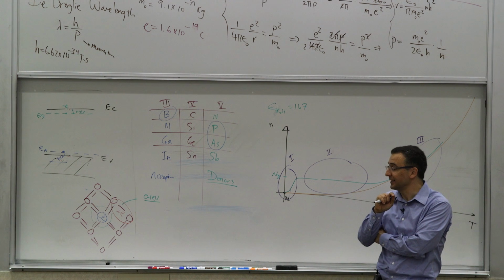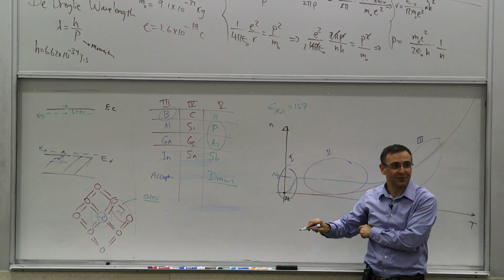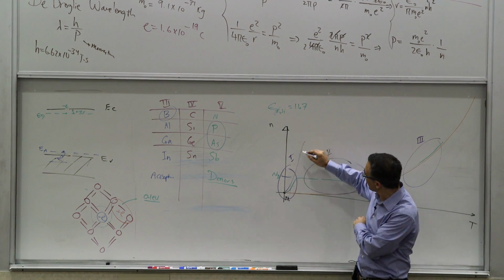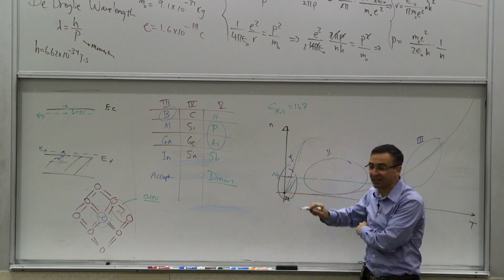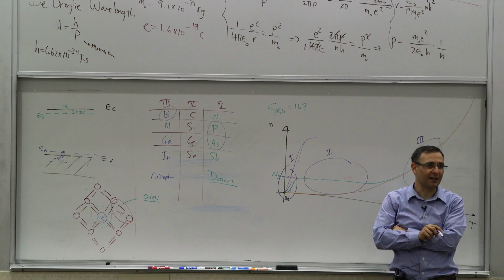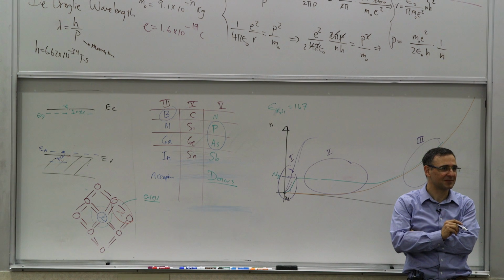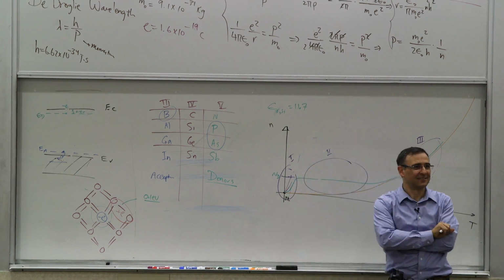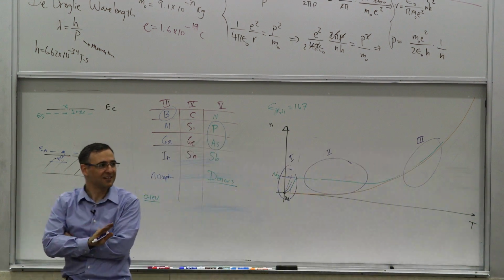Lower ND or higher ND? Now, let's say I want to be at this level, right? So if I start off with ND that would get me up to that much higher level, but it is at that level at that temperature, I can still make it work. They would not be all ionized, but the number that will be ionized will give me the sufficient level that I need. But then it won't work at higher temperature. I just overcompensate for it, right?